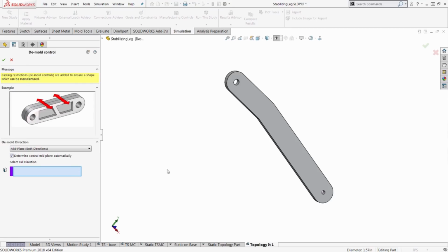And this is interesting because a lot of topology optimization has been commonly clubbed with additive manufacturing, but that need not be the case. Let's say you're doing sand casting or investment casting, or you're just machining this part, right? If you want a web in the middle and you have holes on the sides, you want to make sure that your mold can actually get out, right?